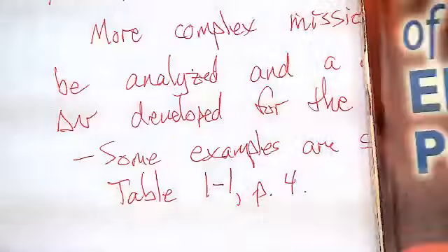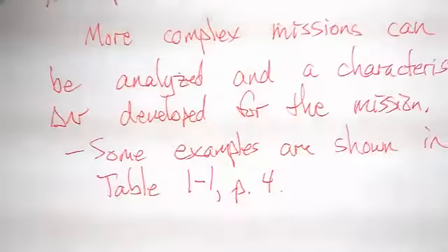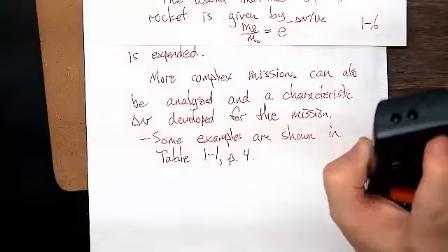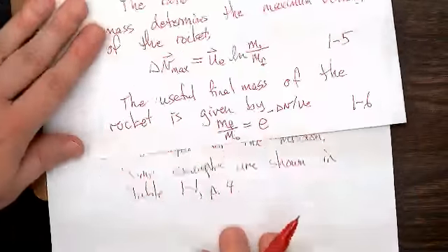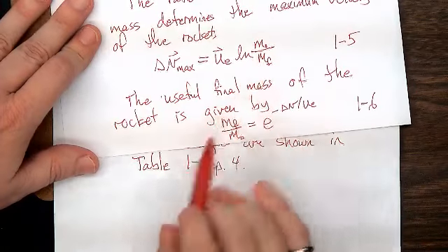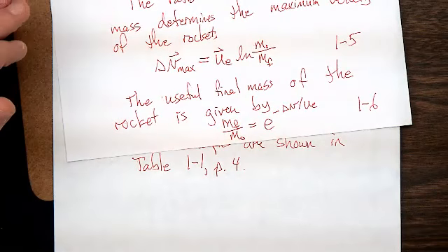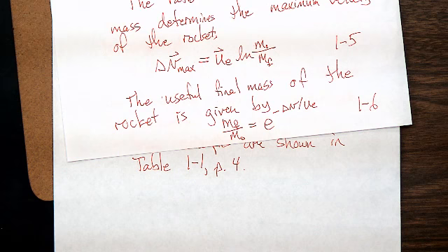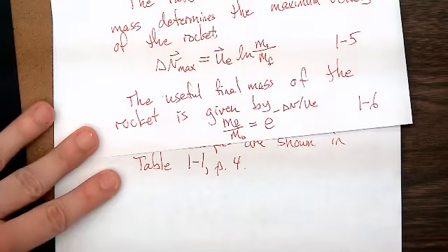And so you can use those numbers in the rocket equation to get a feel for what your payload fraction will be. And note, this M naught over MF isn't payload fraction, that's what's delivered. So you have structure in there, tankage, engines, pumps, things like that, plus the payload. So that all comes out of this M final.